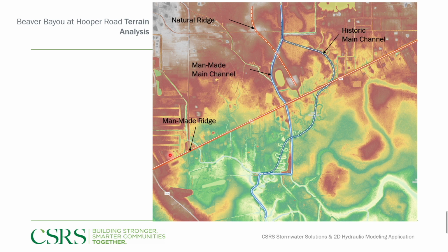We don't want roads to flood, so you're going to elevate them. This road is perpendicular to the flow path of the water. Elevating something perpendicular to the flow path of the water is almost like creating a dam. But we put culverts or bridges so there's something for the water to flow under the road. That's why we put culverts and bridges at certain locations in the road, mainly where there's a channel.